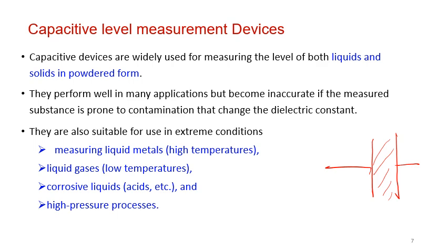So if the dielectric material reaches this much of the two plates, that's going to give me a certain capacitance. As the dielectric increases between the two plates, the capacitance will change. So this is basically the idea we are going to depend on to measure the level by capacitance. You will see this in the next slide.